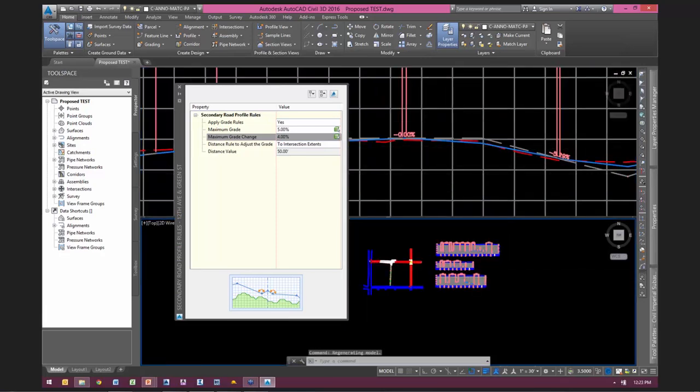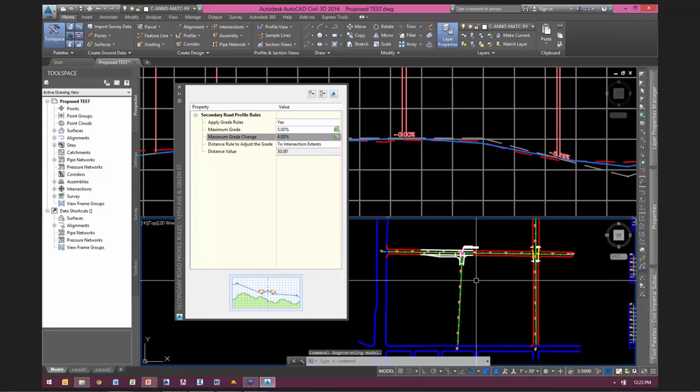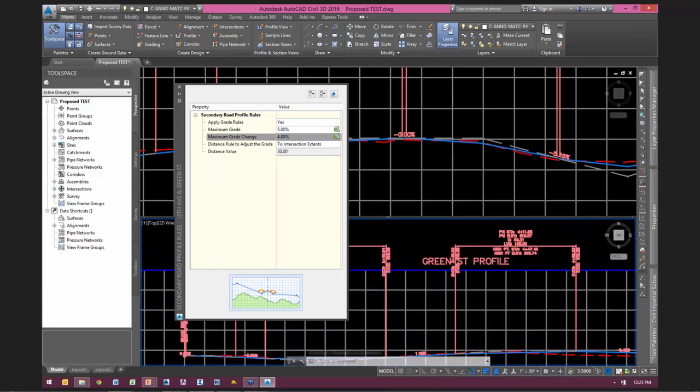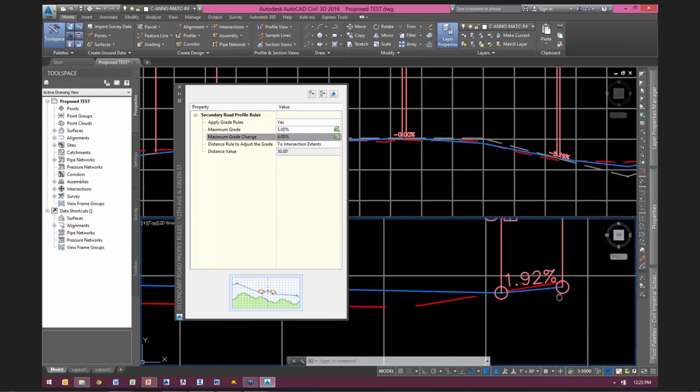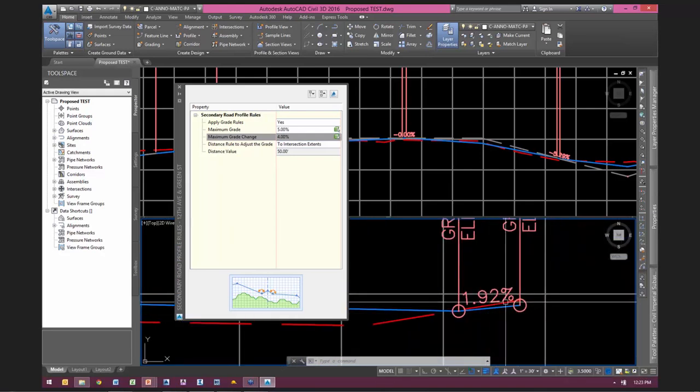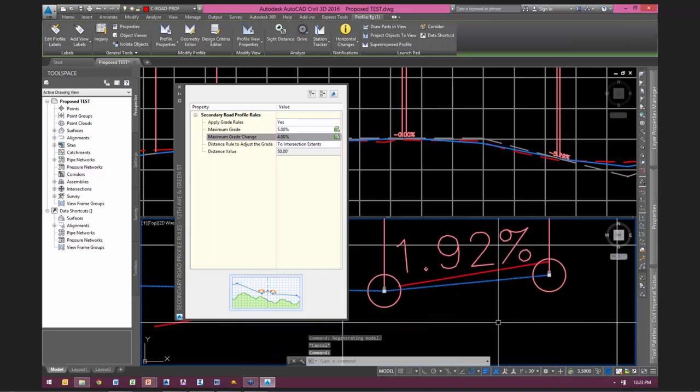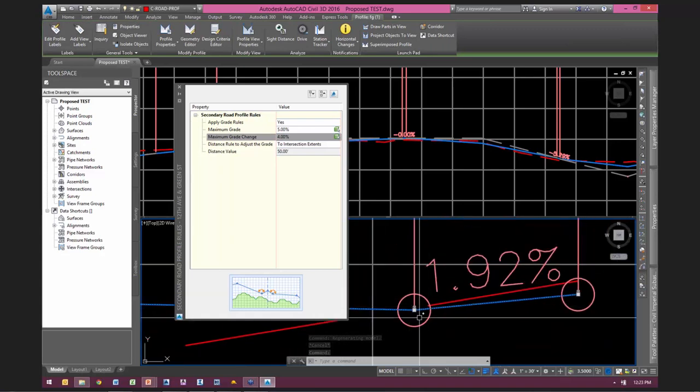And then if in the other viewport I look at the road on the left here, one is called Green Street. I zoom in there. Here's where that profile is tying in at the intersection. So profile locking, absolutely it locks it. In fact, if you click on that secondary road profile, it puts little lock symbols in there, and it also inserts a PVI at the edge of the primary road. So it adjusts these 2 points right here and moves them up and down.